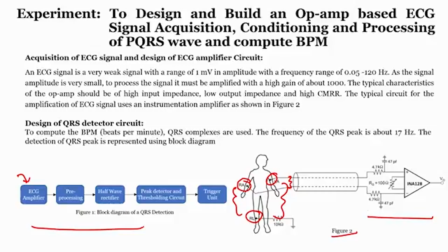So, two voltage sources basically in this case. So, I have to use a proper amplifier or differential circuit in order to take the difference between these two input sources. And moreover, when we observe the amplitude of the ECG signal, the maximum amplitude is within a range of 1 millivolt, which is really small, and moreover it will always have a very low signal to noise ratio.